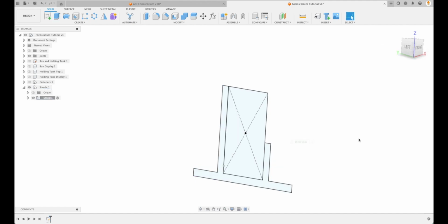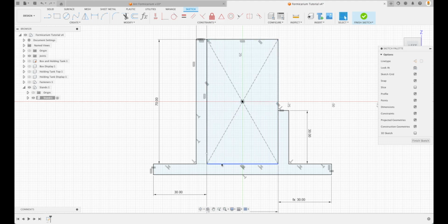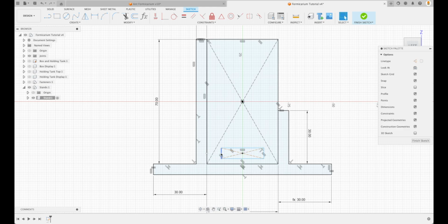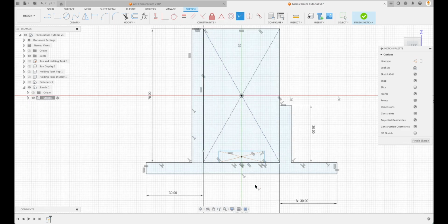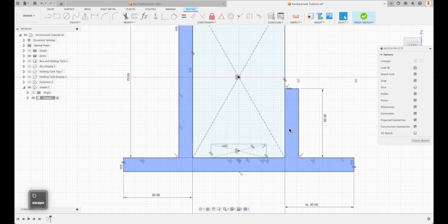And before we do that, actually, I'm going to go back to the sketch and create a little bit of kind of a fun little thing to do here. Let's go to our center rectangle and I'm going to create just a couple reliefs. But remember with 3D printed materials, if we have sharp edges, they break a lot easier. So I'm going to create some big loopy rads and fillets so that our stand is a lot stronger. So let's go collinear there to there. This is going to be vertically constrained right to there.